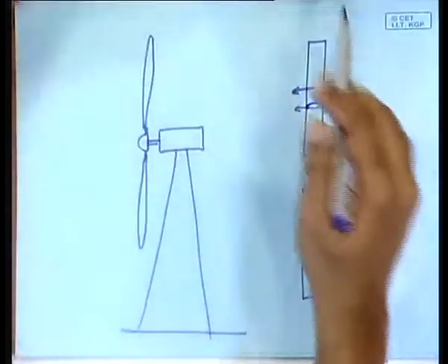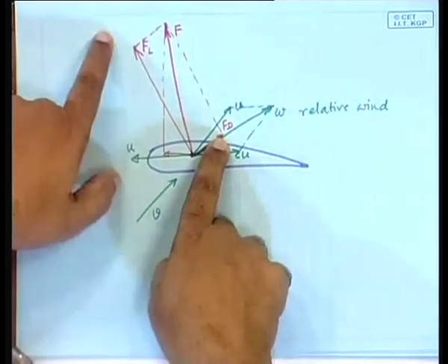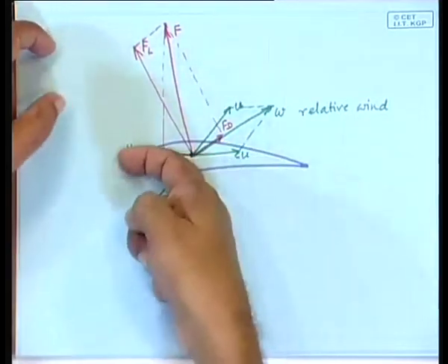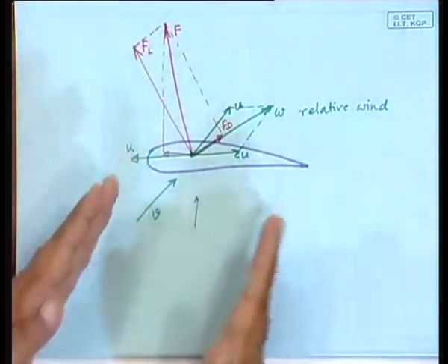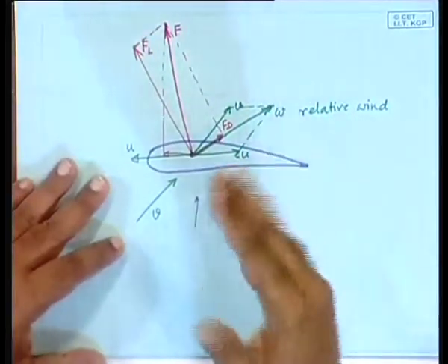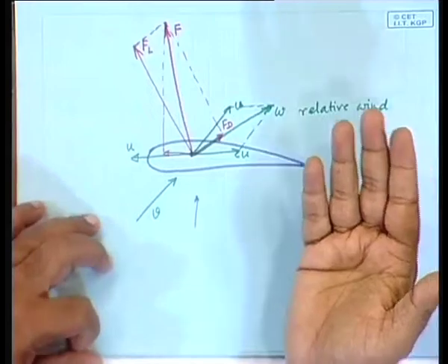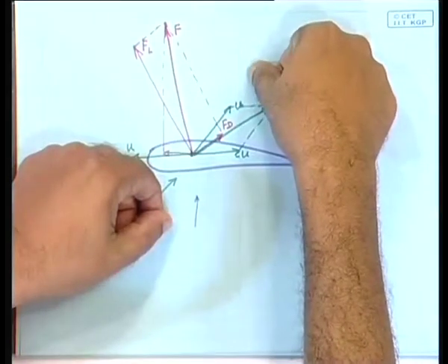And normally, okay, it will not be difficult for you to understand at this stage. See, you would like to minimize the drag and maximize the lift, because drag is acting in the opposite direction to the lift. The more the lift, the more this force. So, you want to reduce the drag, and what was drag proportional to? How much area the wind sees, accordingly it tries to push back. So, you would like to make sure that it sees the least area, and when does it see the least area? When this airfoil is oriented in the direction of the relative wind.